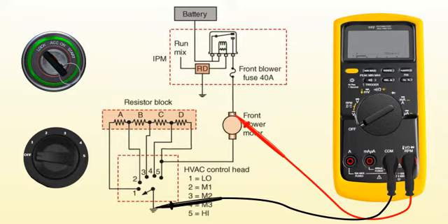The blower circuit operation. Battery voltage will flow through the circuit starting at the battery, moving through the conductors to the relay contacts and relay coil. Battery power will not pass any further since the relay coil does not have a ground to complete the circuit and the relay contacts are currently in their normal position, open. When the ignition switch is rotated to start or run, the blower relay receives the ground to complete the circuit and energize the relay. When the relay coil is energized, it will become magnetic and pull the contacts down. Battery power will now pass through the relay, through the fuse into the blower motor.